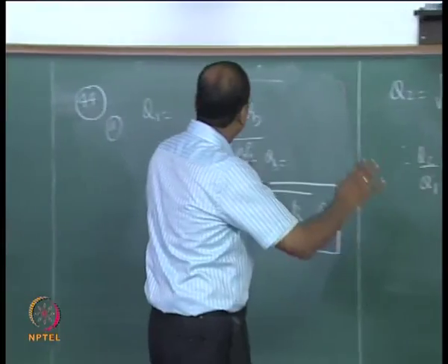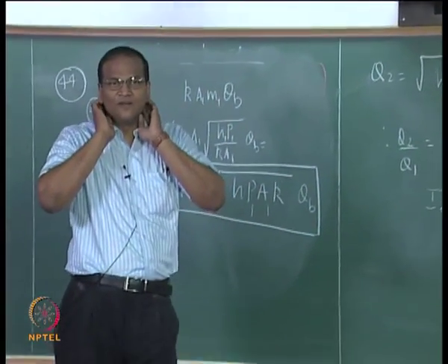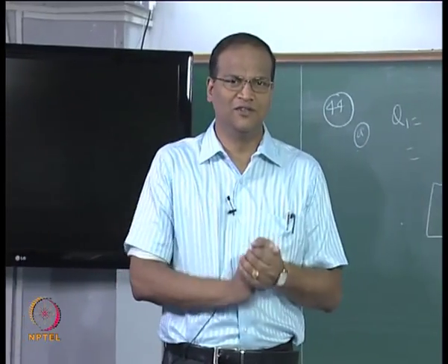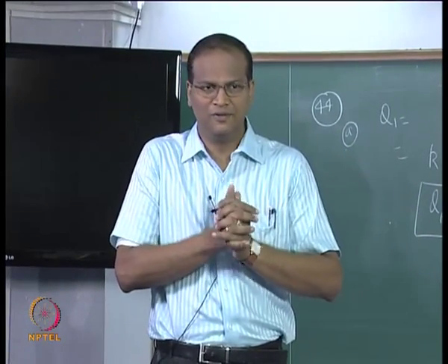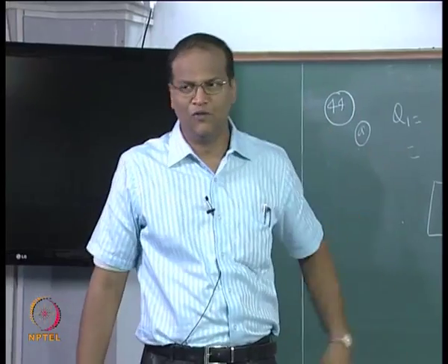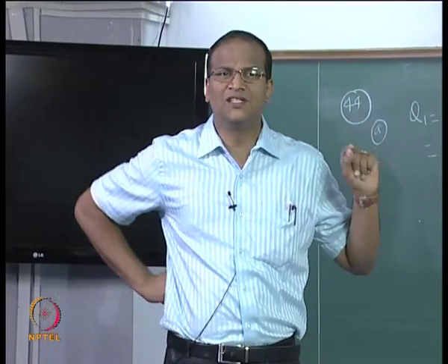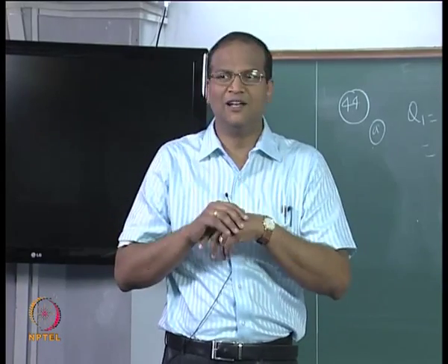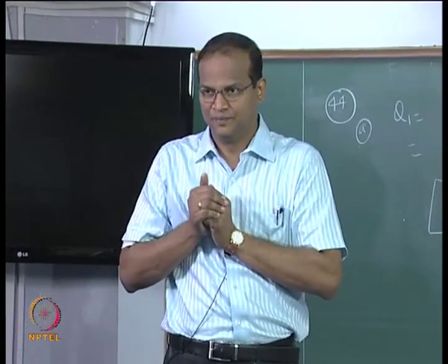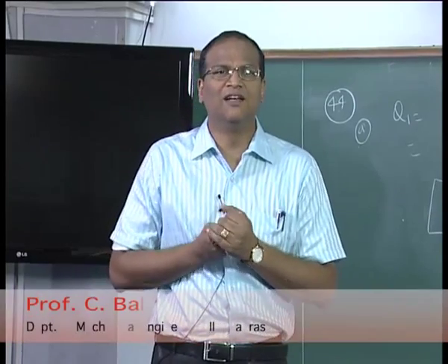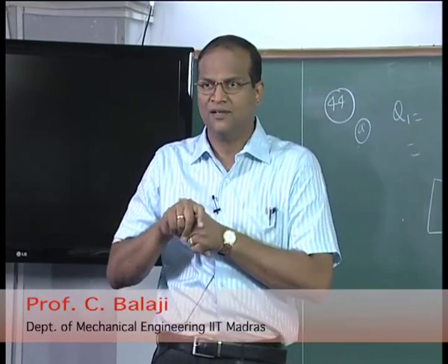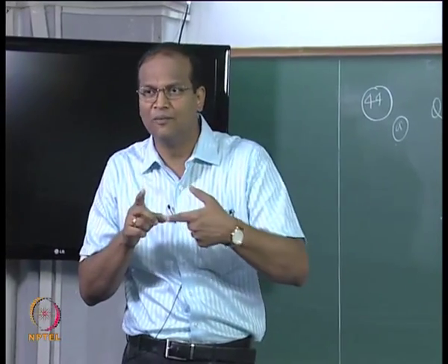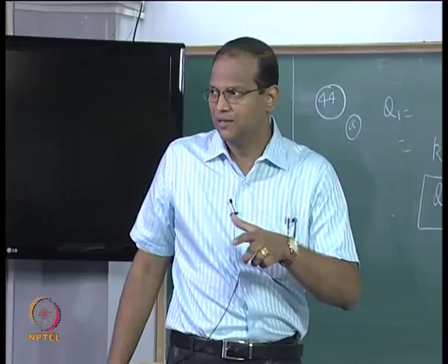Now you can see this sort of exercise gives you an idea of the basic heat transfer processes, how each of these parameters influences the heat transfer rate. So this gives you a good idea of the role of various parameters. I can also conduct some experiments where I have a long fin, I measure the temperature at 2 places. Then I know that theta by theta b is e to the power of minus mx. Now I can solve it as an inverse problem and get the value of m. From the value of m I can get the value of thermal conductivity.